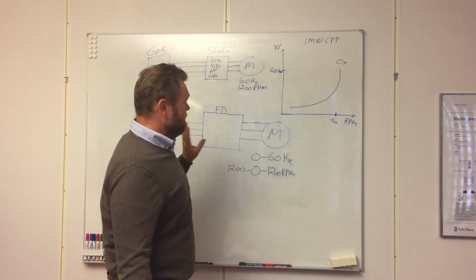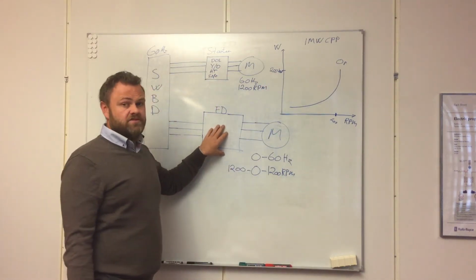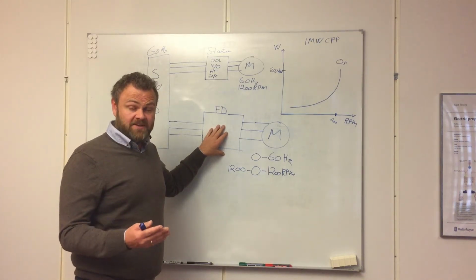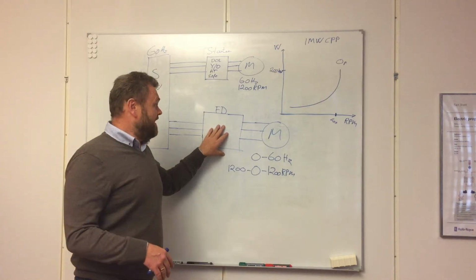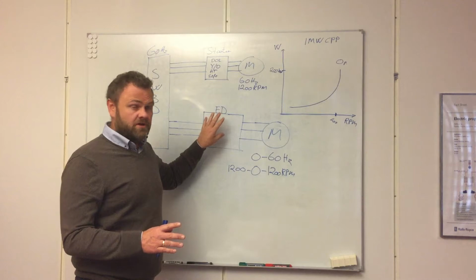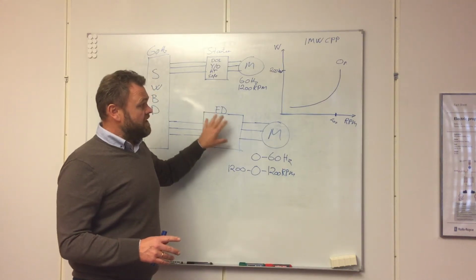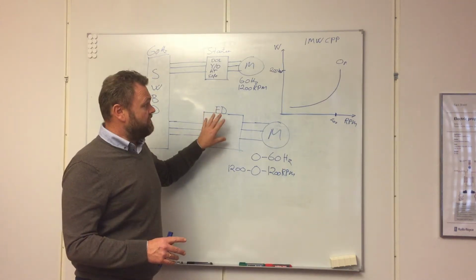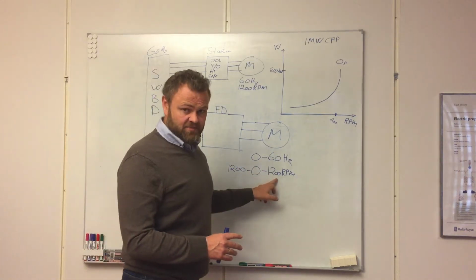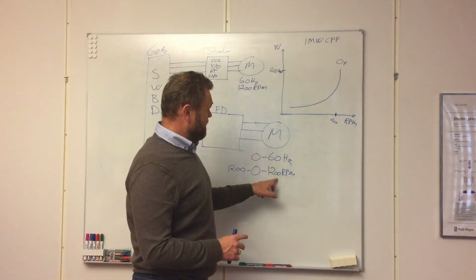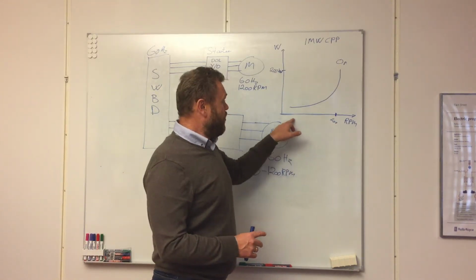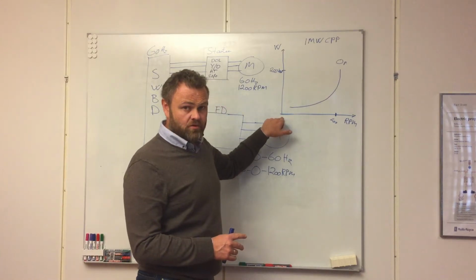So if we then introduce a frequency drive, it will increase the capex for the ship owner. He has to pay for this frequency drive up front. However, the frequency drive will give you the opportunity to reduce the speed from nominal speed and all the way down to zero speed.